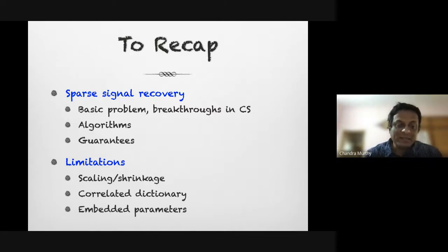They build a specific hardware which incorporates a measurement matrix into the hardware. So that way you can acquire compressed images directly rather than acquiring a full complexity image and then running some compression algorithm like Lempel-Ziv compression to compress the image. You can directly acquire a compressed image using these single pixel cameras. They use some specialized hardware, and that specialized hardware specifies the sensing matrix. And you need to know what that specialized hardware is doing while it's acquiring the image, because you need to know what phi is in order to recover the image back from the measurements y.